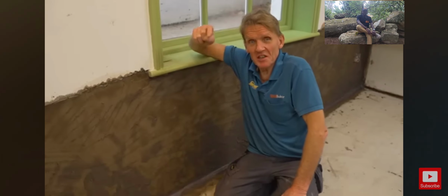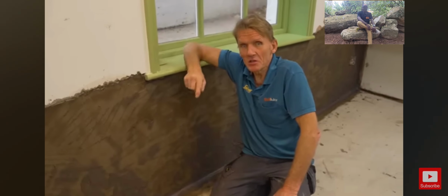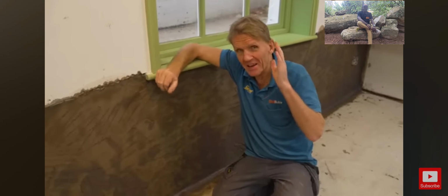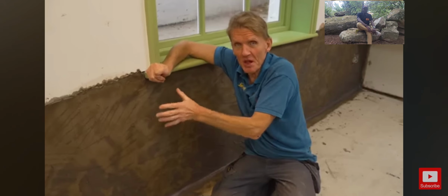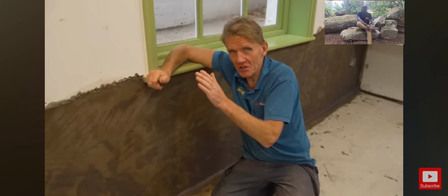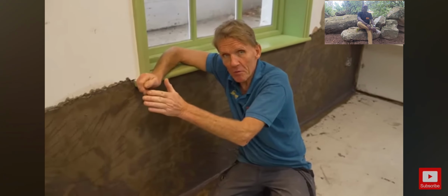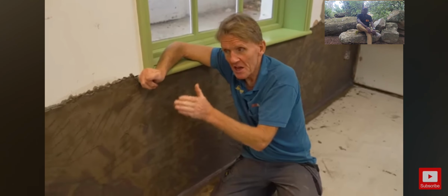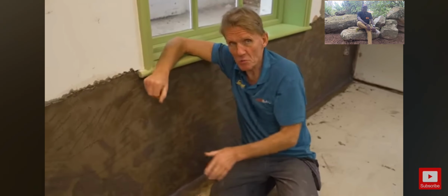So this is actually tested for 50 meters of head, which is a huge amount. But we've got to remember, this is done in a laboratory and it's done with flat concrete, really solid concrete. When you're doing it in an actual Victorian sand and lime construction basement, you're talking about very different things. So that's why we level it out with that coat of render, that SBR, just to give us a nice flat surface and give it the maximum chance of working.